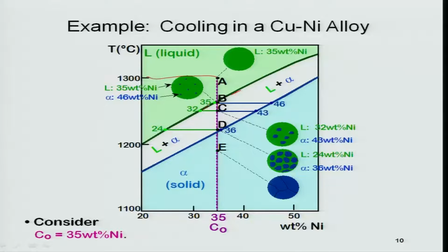As you know, at the melting temperature or the liquidus temperature, the Gibbs energy difference between the solid and liquid phase is 0. So there is no available energy which can be spent to create the interface between solid and liquid, and that is why you need to cool down below the liquidus to form solid alpha.